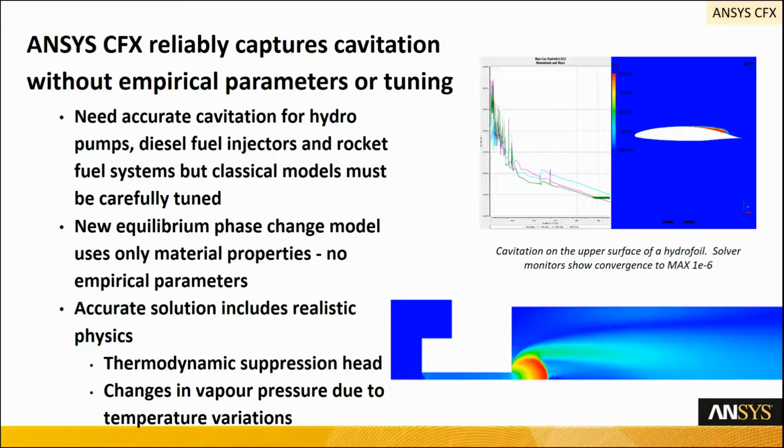Okay, we'll move to CFX now, and in particular there are some important updates that occurred at 19.1, so we'll start with those. One of the main ones is the ability to perform cavitation simulations using solely a thermodynamic model.